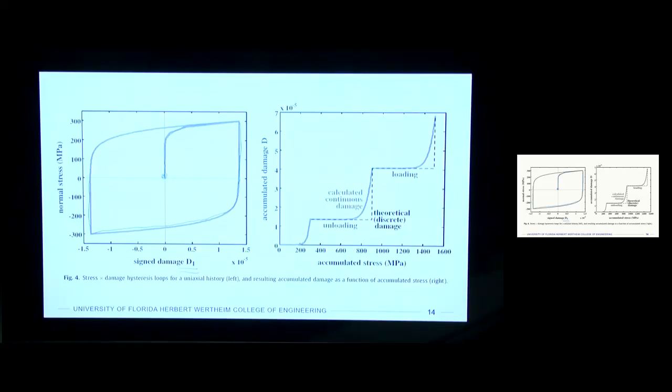And then it's going to cycle back up and do just a positive, negative, fully reversed normal stress. Okay, so that is a very simple experiment that has one fully reversing cycle, right? And so then they say map out on the right side what that looks like in their accumulated damage model. So the y-axis is that accumulated damage, and then on the x-axis, they say accumulated stress, okay? And so you have to look at the stress over time and how that's being applied.